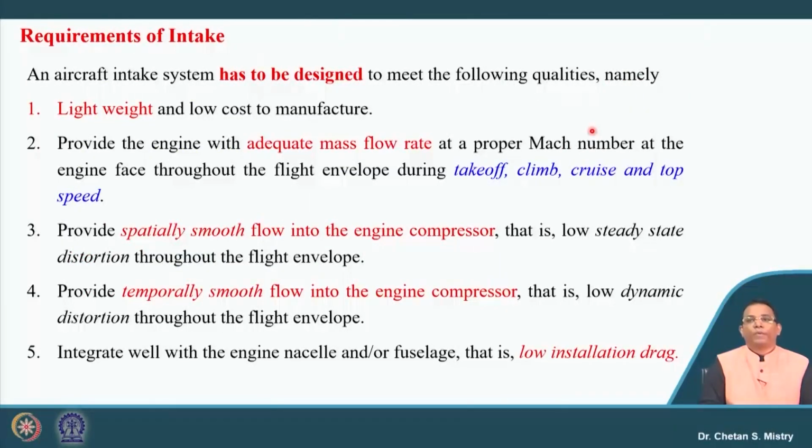Now what are the requirements for this intake? Suppose you are given a task to select or design the intake, what will you be looking for, because that is also equally important. It should be lightweight and low cost to manufacture. We must realize we are talking about the aero engine, where our requirement is maximum fuel economy. When we say fuel economy should be higher, that means my drag should be as low as possible. That's what requires a lightweight configuration. So the intake should not be heavy.